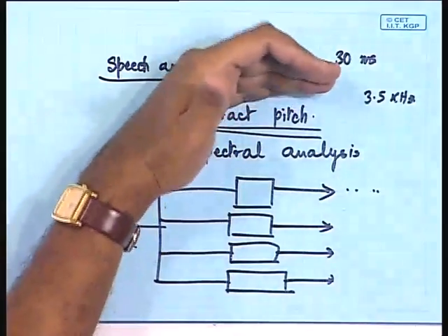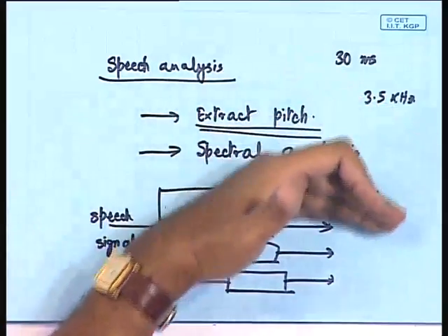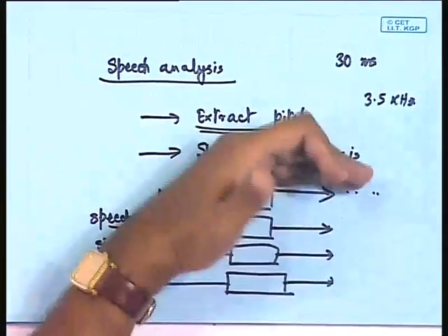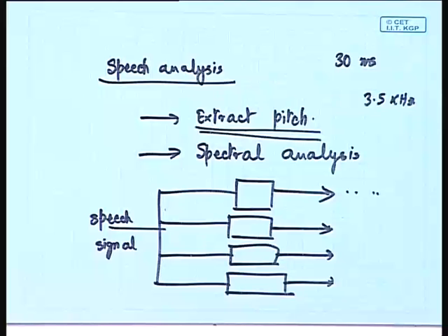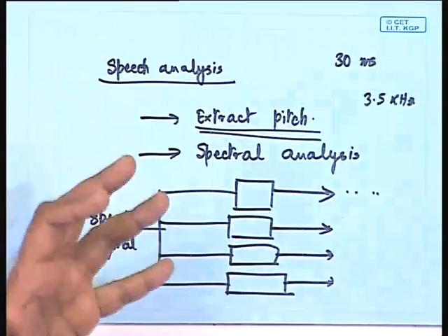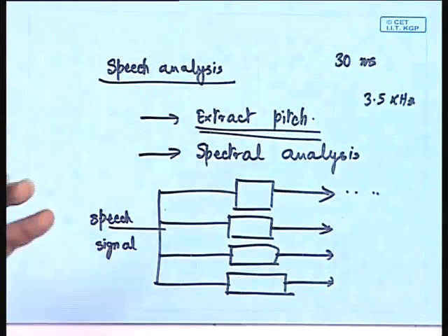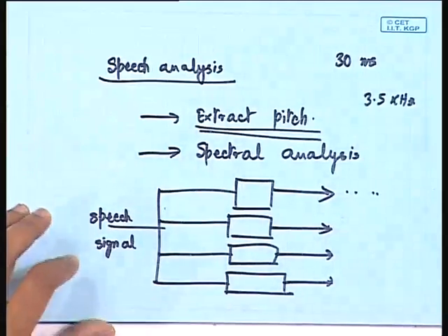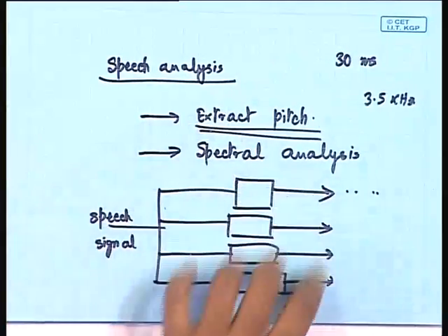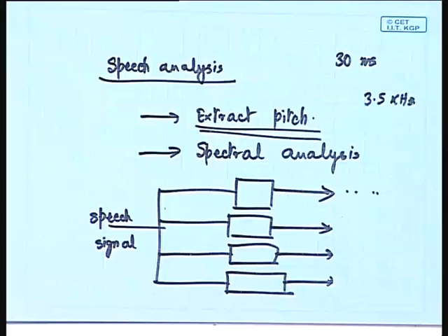And not only that, there is also one more point which you should keep in mind: by having a speech analysis and only giving the pitch information and the individual band energies, and also of course you have to give another flag information, whether it is voiced speech or unvoiced speech. If it is unvoiced speech, then one has to switch on a noise generator in order to do the speech synthesis. So, this sort of information representation also will be more compact.